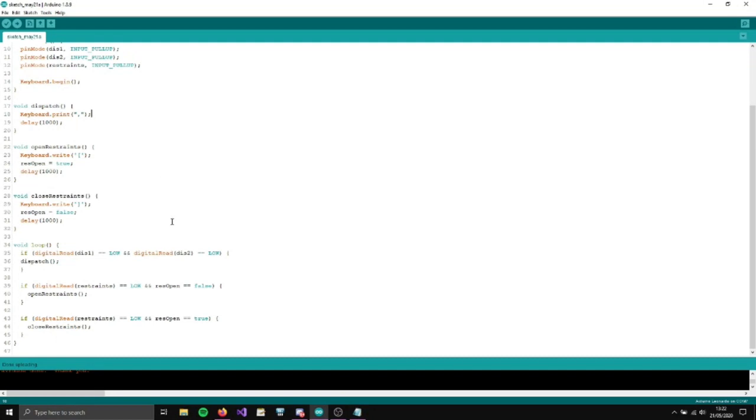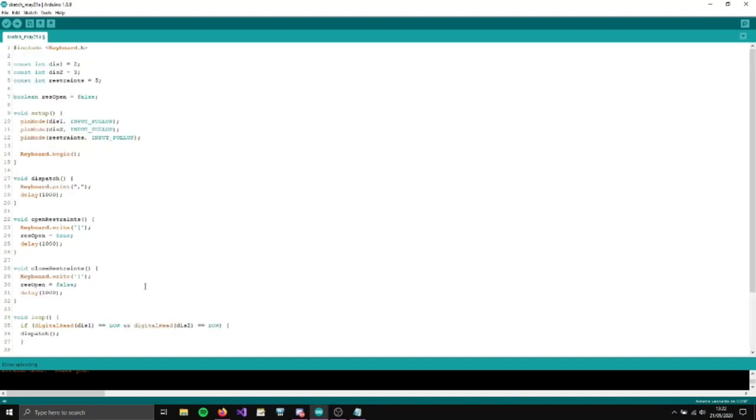Okay, so now I'm going to program in a gate switch. Gate switch, obviously, quite important. So we're going to declare what pin we have our gate switch as. This is just like a regular selector switch. You can hear it. And I put this on the panel. You saw it earlier. It's basically the same as the yellow button, except normally it won't have electrical current flowing through it when it's pushed to the left, but as soon as it goes to the right, it will have constant electric flow through it.